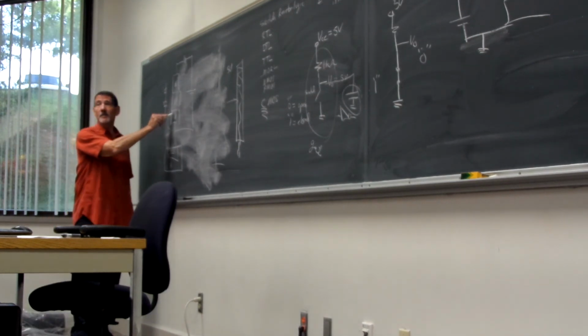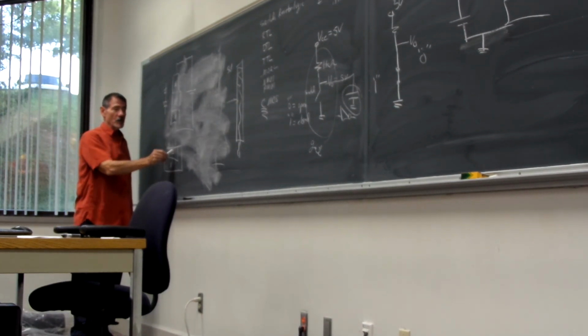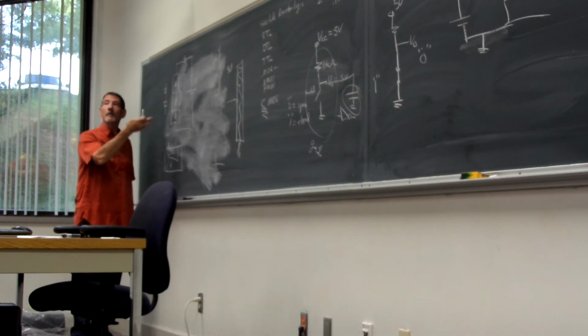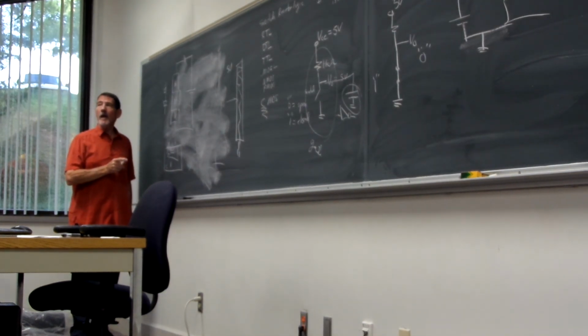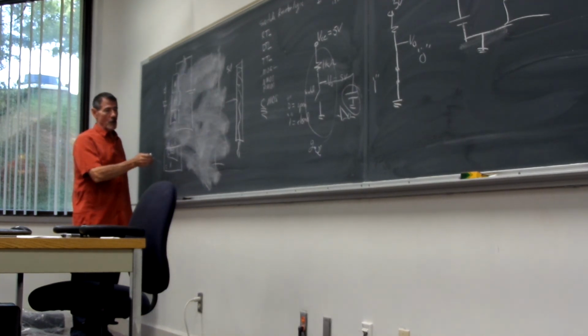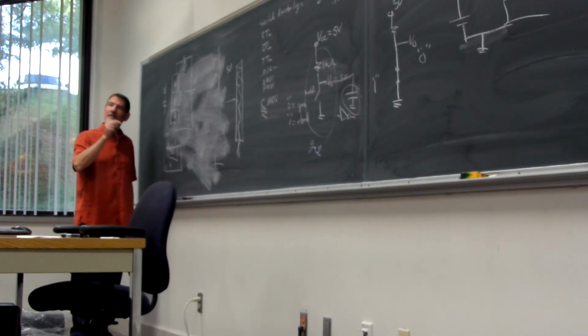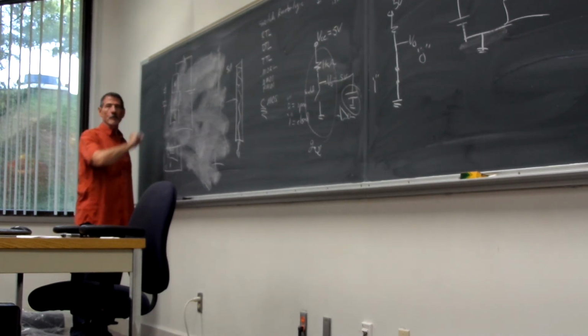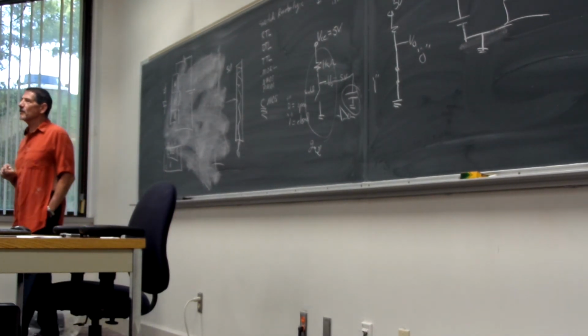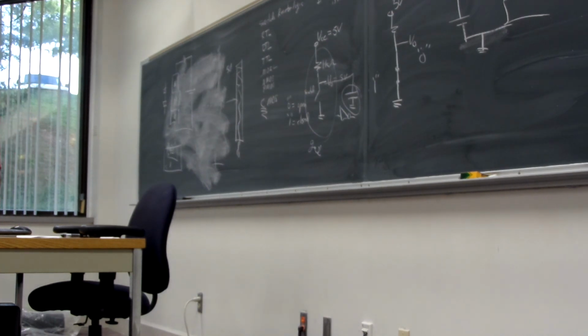We're back to this guy here. But if I inject a small amount of current in here, then I can open that thing up. And with the BJT transistor, when you put a lot and a lot and a lot of current in there, it goes to a voltage of about 0.3 volts. Okay, it's saturated.